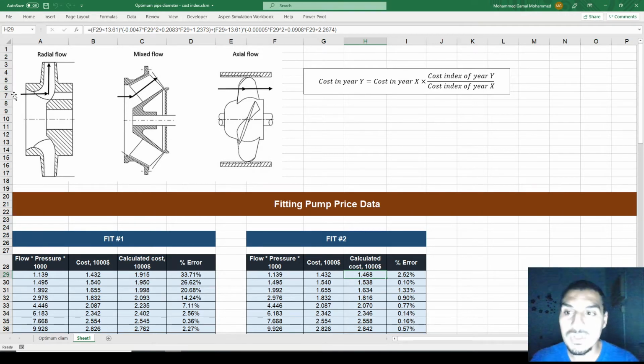That's why conventionally the flow will go into the pump and change its direction to be perpendicular to the original flow direction. So it's going horizontally and then it goes out vertically, and this is pure centrifugal force, and this is why it can give very high heads compared to the other types. So this is the way it works, and that's why this is the first choice when we think about centrifugal pumps. This is the radial flow, or the conventional flow, the first thing that comes into our mind.